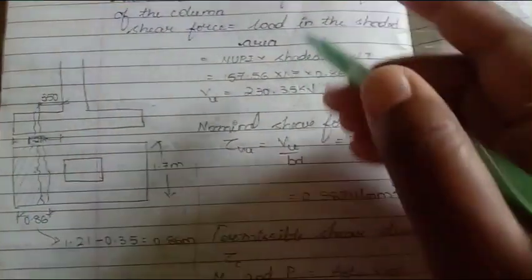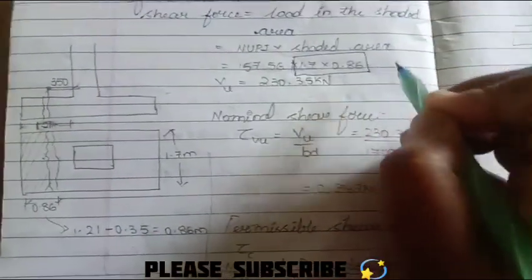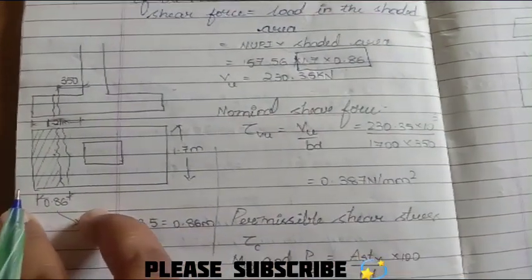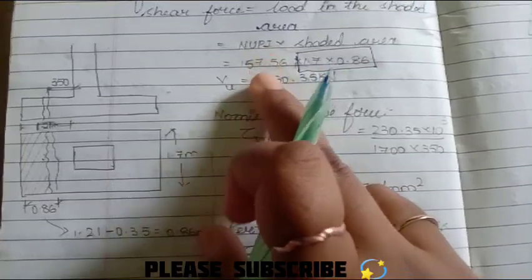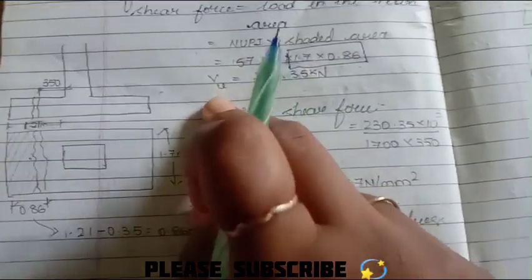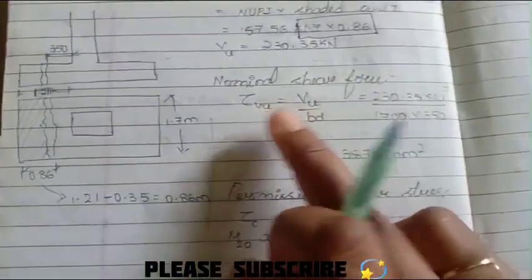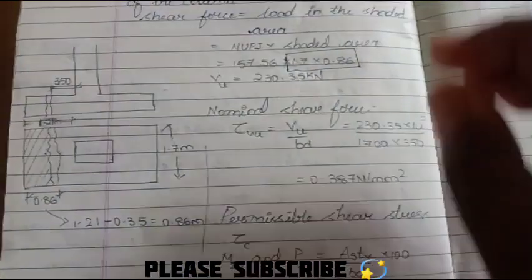So here the shaded area is nothing but 1.7 multiplied by 0.86. This is the 1.7 value, this is 0.86. So this area multiplied by the net upward pressure intensity, we'll be getting the shear force. Force is nothing but stress multiplied by area. This is the ultimate shear force we have calculated.